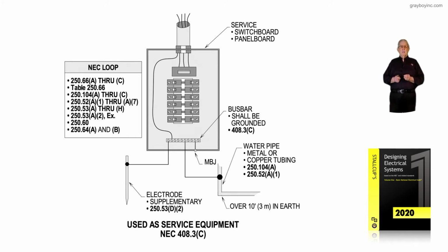For example, let's use 4/0 conductors entering through the service raceway, terminating to the main, which is 225 amps. Based upon the 4/0 conductors, we would go to Table 250.66, and that would be a number 2 grounding electrode conductor that would connect to the metal water pipe or the structural steel, using the value of number 2 copper selected from Table 250.66 based upon the 4/0.